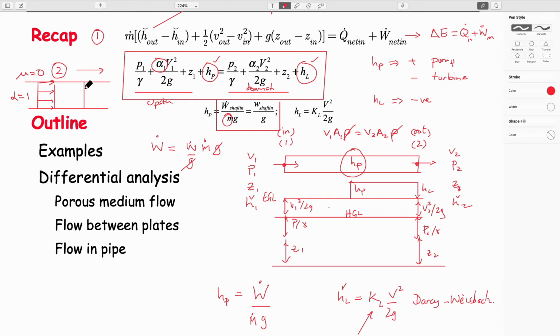If viscosity is real and finite, then the flow regime looks like this, because we know from Newton's law of viscosity, clever guy, this Newton, dvx/dz, that the boundary condition is typically that the fluid sticks to the wall at the edges, giving zero velocity there, and there's a parabolic distribution between.